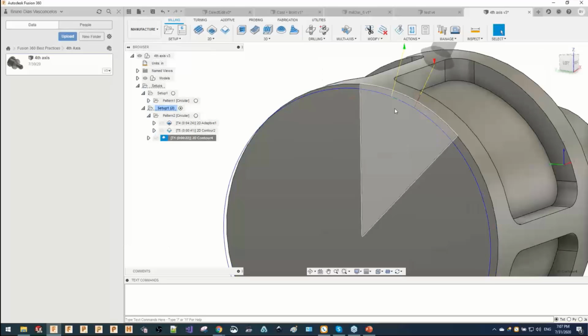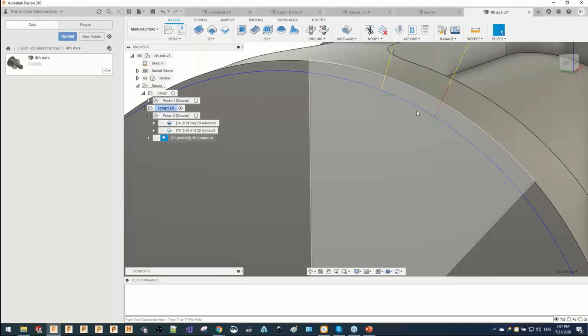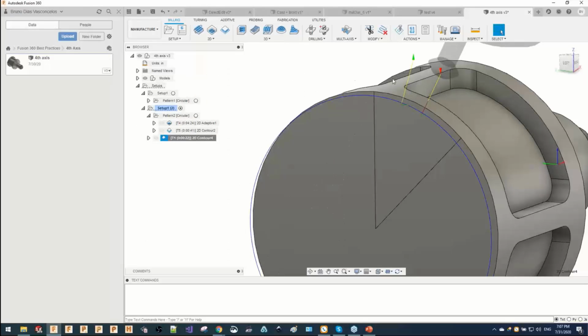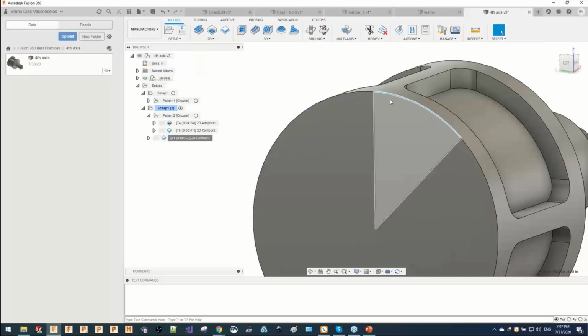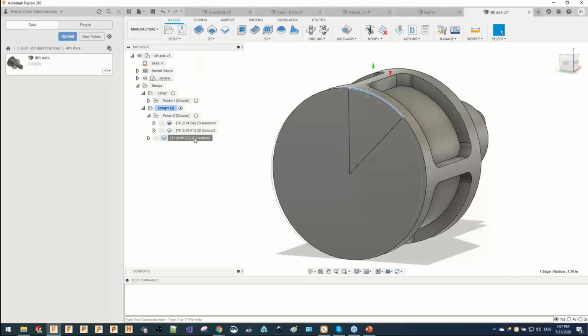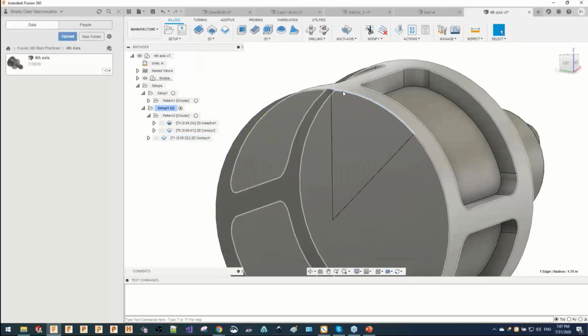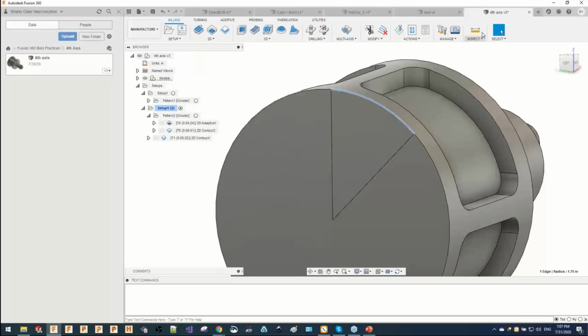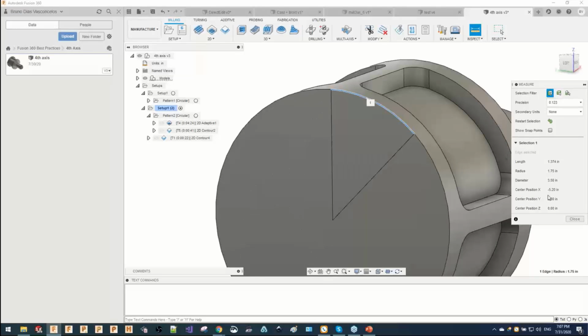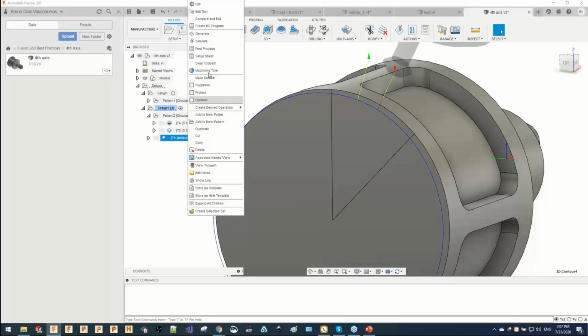This thing that you're having here is an overlap. Because the 0.8 or 1 inch that I have extended is longer than this chord length. So in short, if you don't want to have any overlap, you need to calculate the chord length of this. I'm not sure if there's a way to do chord length here. It's 1.374. So you can use that in your extension.